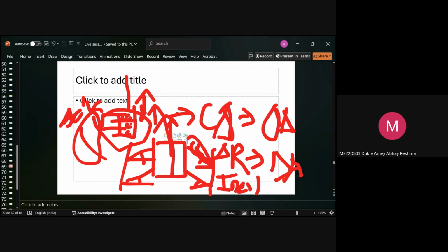Capacitor type is more advanced because there is no moving part. Anything that has limited inertia, when the mass is low, the inertia is less. So that is why the capacitor base is more accurate, whereas this piezoresistive one is less accurate. This big block, although it's big only in the micro sense, because of the inertia would not come back to its original position that easily. So it would not give that good reading, whereas a capacitor will give better reading.